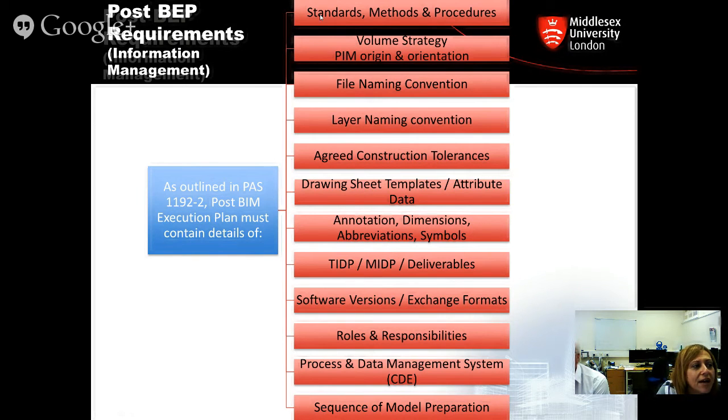So you should have what kind of the teams should collaborate together, and a common BIM manager or whoever the person who is responsible for creating the BEP, whether it be from the client representative or whoever is agreed to be the person to actually write this down. According to the collaboration between the teams, there should be an agreement on what kind of standards are going to be used for the methods and the procedures throughout the project.